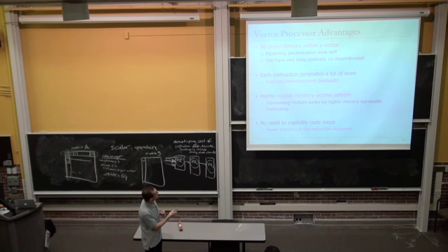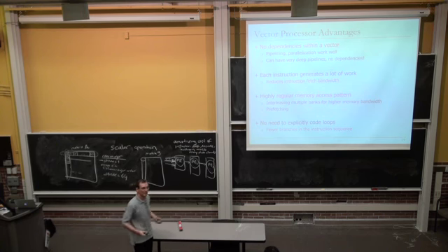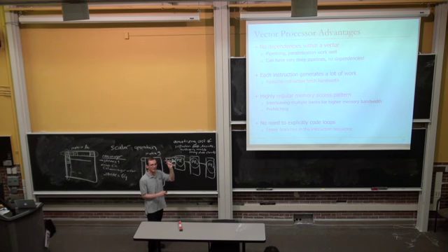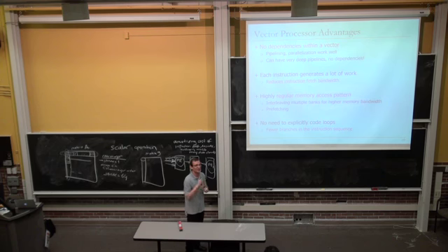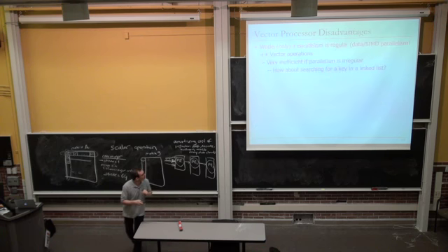You have a highly regular memory access pattern, assuming you're operating on vectors, of course. And we will see how this is a good thing as well as a bad thing because of the parallelism, right? You have a lot of parallelism, which means that you need to supply the data if you're loading the vector. Whereas if you're fetching from a single instruction, you need to supply only one element, right? But a highly regular memory access pattern helps you to actually prefetch data, if you will. And there's no need to explicitly code loops. You can eliminate branches with this, and we will see that as well.